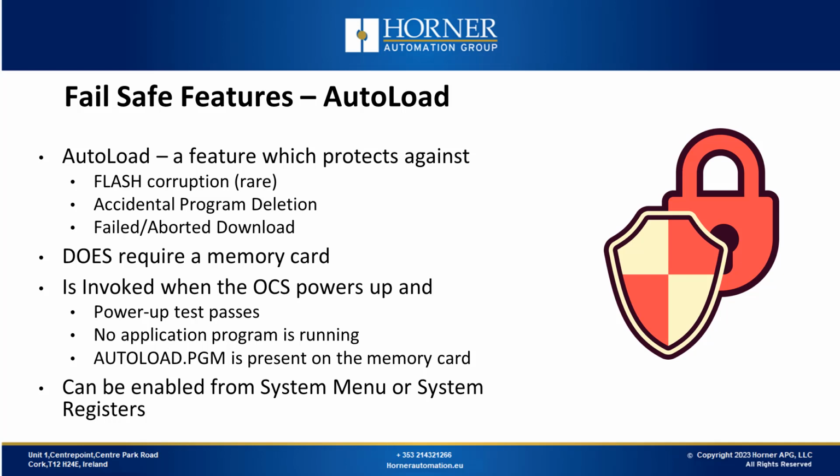The next fail-safe feature we'll discuss is auto load. Auto load serves to protect against flash issues, including rare flash corruption as well as accidental program deletion. This can happen if someone inadvertently deletes a program in Cscape, or more commonly due to a failed or aborted program download, leaving the controller without a valid program.